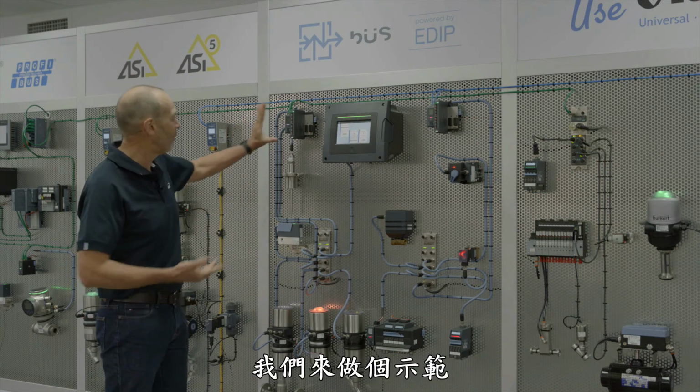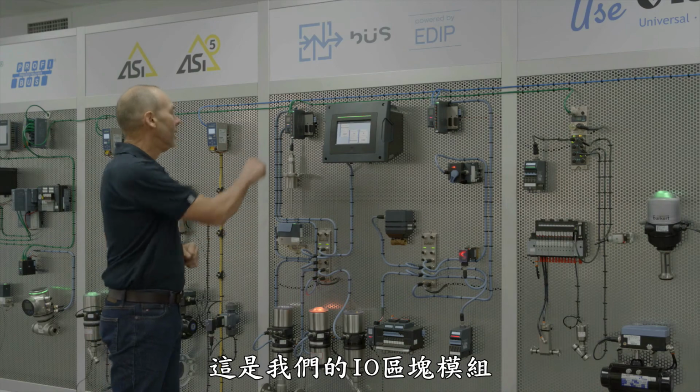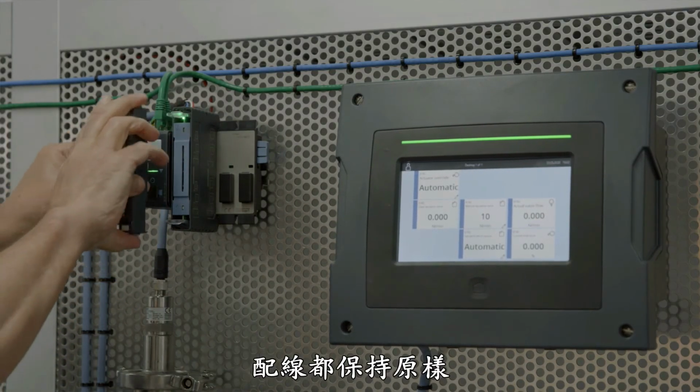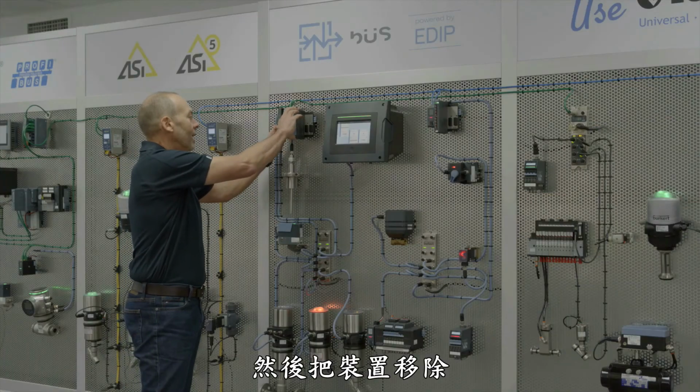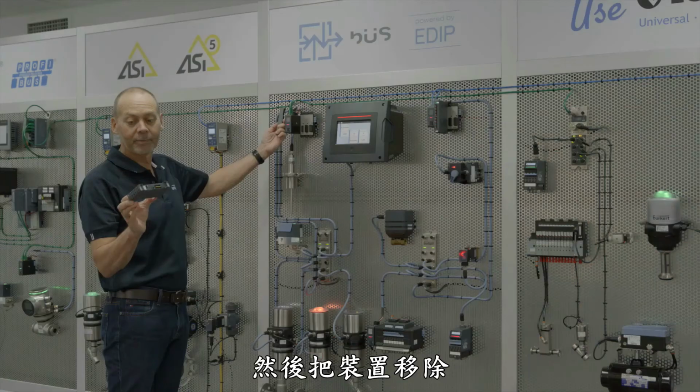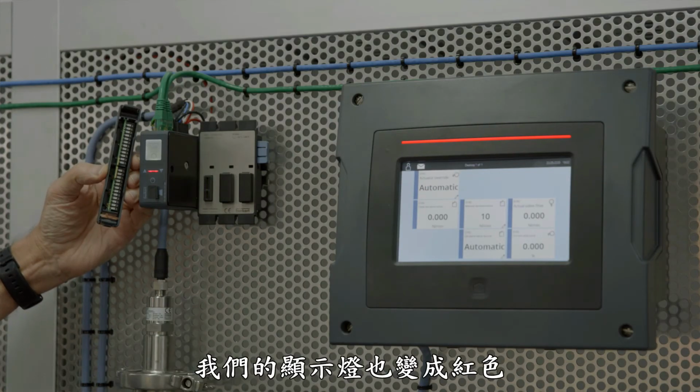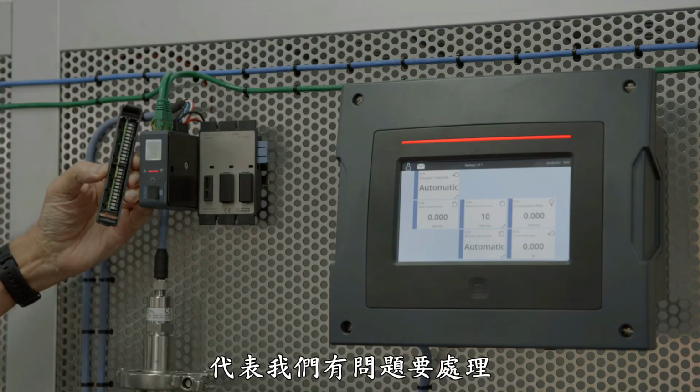So just to give you an example, this is one of our I/O modules. I'm now going to disconnect that where the wiring would normally be. So the wiring would stay intact and I would remove that. I can now remove that module. So I've taken it out. I could put a new module in. You'll see that it's gone to red and our indicator has also turned red that we have a problem.